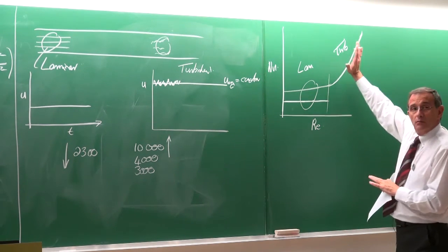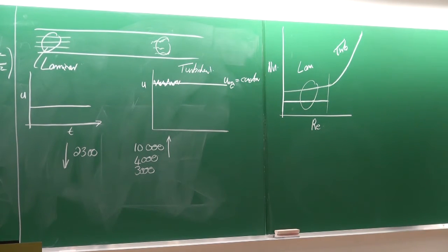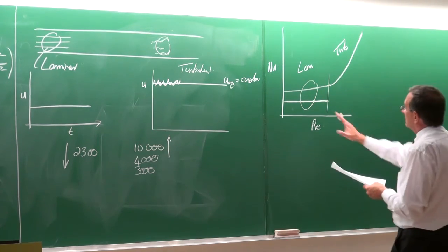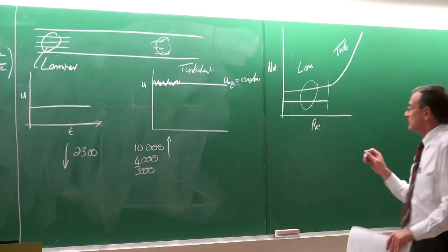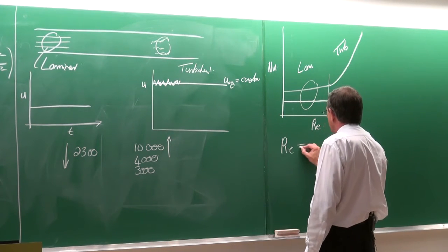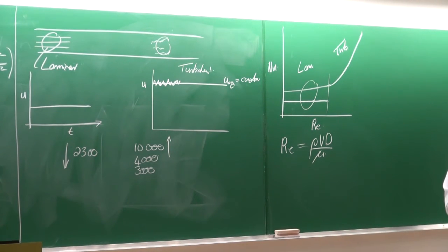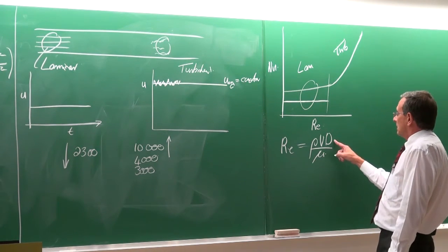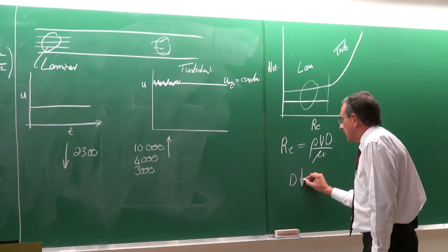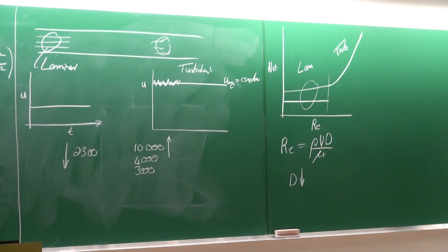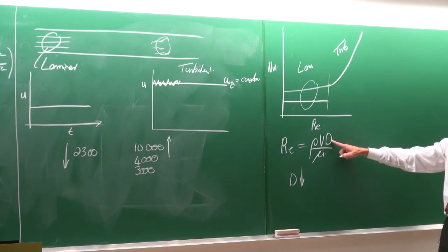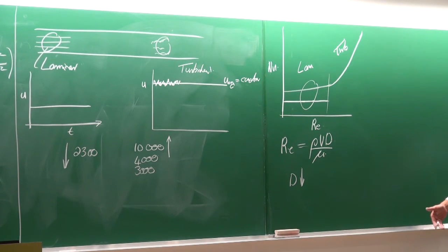In industry, mostly you work in a turbulent flow regime. There are not many applications where you work in the laminar flow regime, but it sometimes happens. When will it usually happen if we look at the Reynolds number? When will it normally start becoming very important? It will start becoming important if the diameter becomes very small, so in microchannels, typically used in the cooling of electronic applications. If you make this smaller and smaller, you'll see the Reynolds number becomes smaller and smaller.